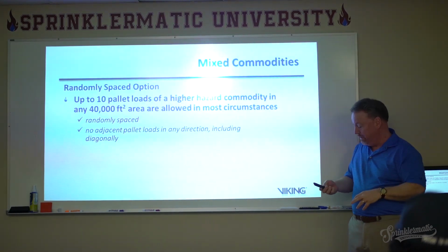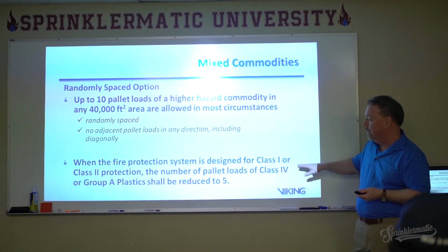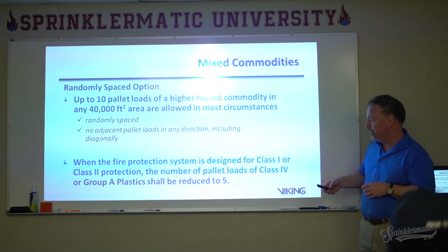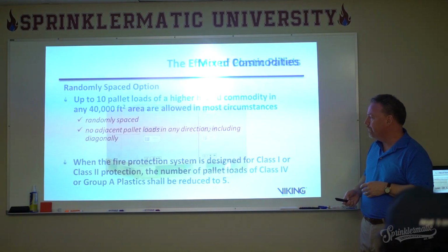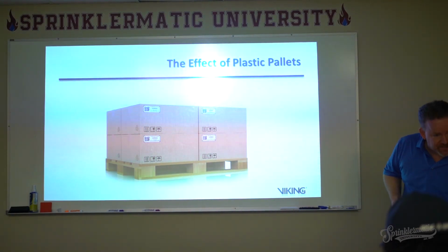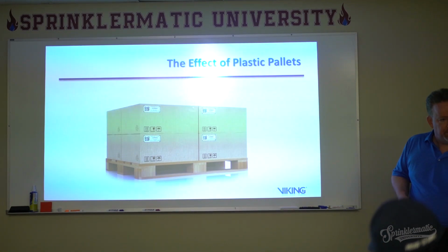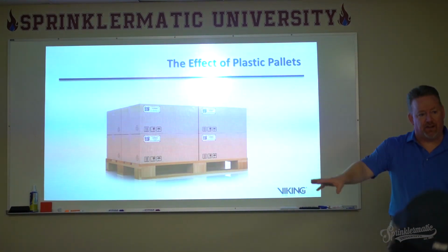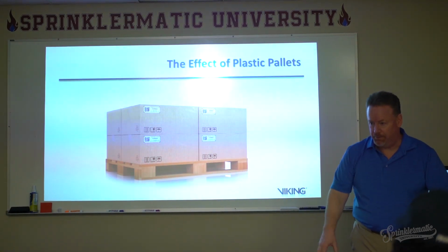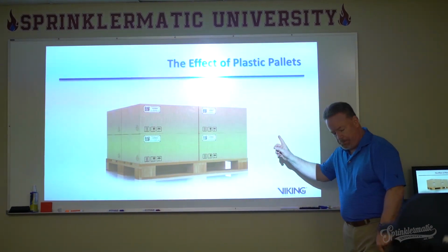Keep in mind these mixed commodities and the challenge with this. We're also going to note that the number of pallets of Group A can be reduced to 5 when the fire protection system is designed for Class 1 or 2. So that's the impact of Group A plastics on others. That's the mixed commodity requirement, or the mixed commodity challenge.